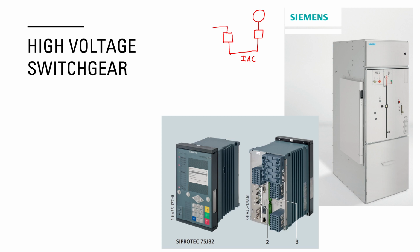Then that will go through a transformer, where it will go to a higher voltage piece of switchgear, and that will go through the export cable to onshore, where it will go through another piece of switchgear, and then it will go through the onshore transformer, and then it will go through at least one, but probably more likely two pieces of switchgear before it connects to the grid. So from the turbine, you've got 1, 2, 3, 4, 5, and probably 6 pieces of switchgear between the turbine and the grid.